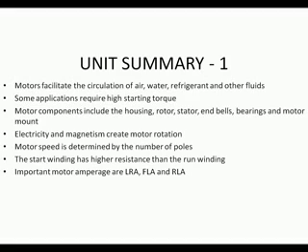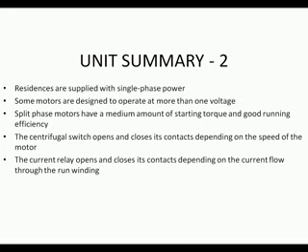All electronic motors must be cooled. Hermetic compressor motors are cooled by both the air and the refrigerant. Open motors are cooled by the air. Open motors must be located where there's a good supply of air, and some very large motors can be cooled by water. So we've talked about the motors, the facilitation of the circulation of air, water, and refrigerant.